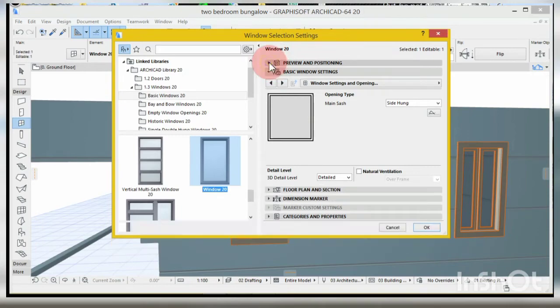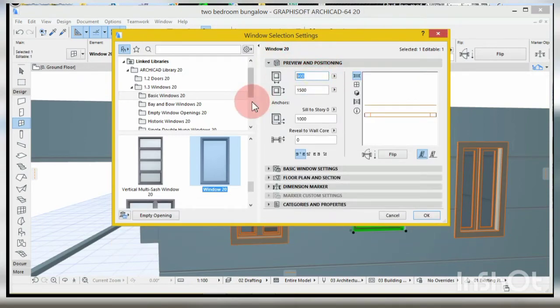So this toilet window, I will just use this. It's going to be a sliding window anyway. Toilet windows depend on what I want. So I can easily type 750 by 750. You can type 600 by 600, any one you want. So this I'll type 1650.